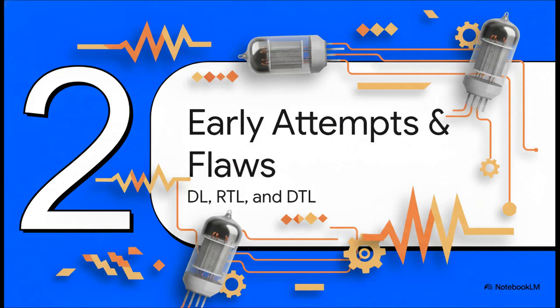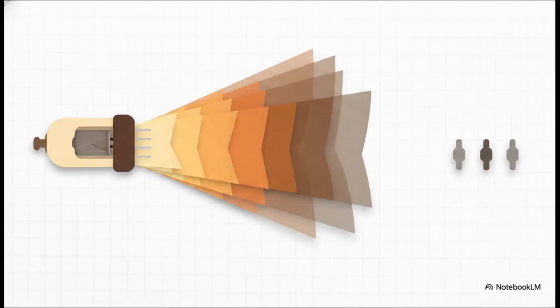Section 2, early attempts and flaws. Let's talk DL, RTL, and DTL. So, diode logic. It was the absolute simplest architecture you could possibly build. But man, it came with some massive drawbacks. Think of its voltage degradation like a really weak flashlight beam that just kind of fades out over a distance. It literally couldn't push signals very far down a circuit board.